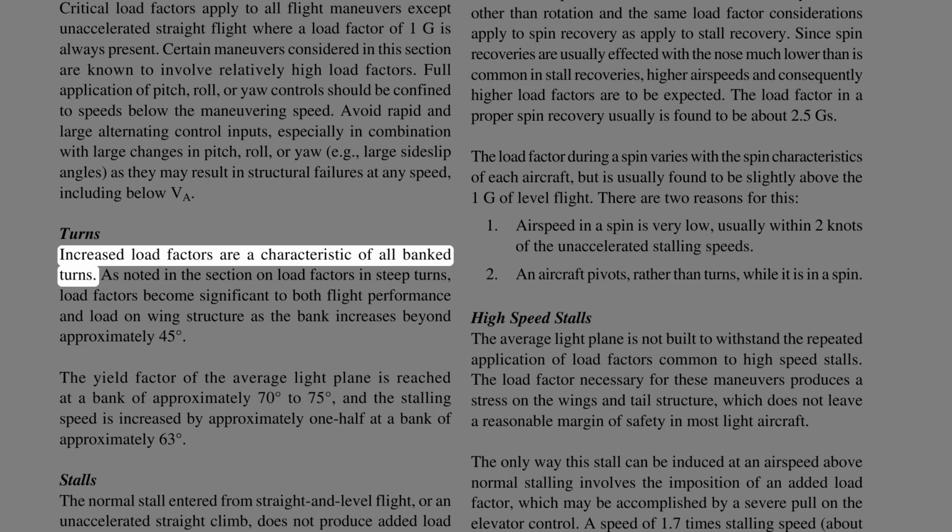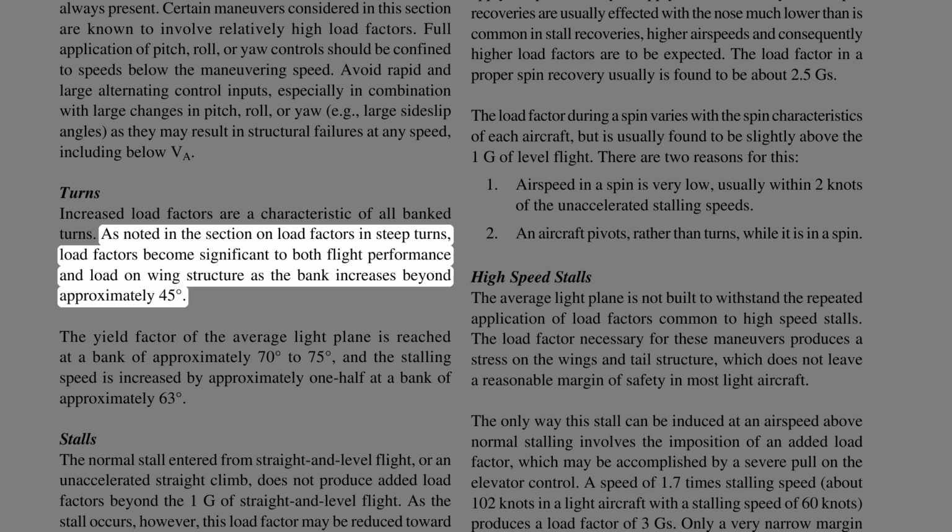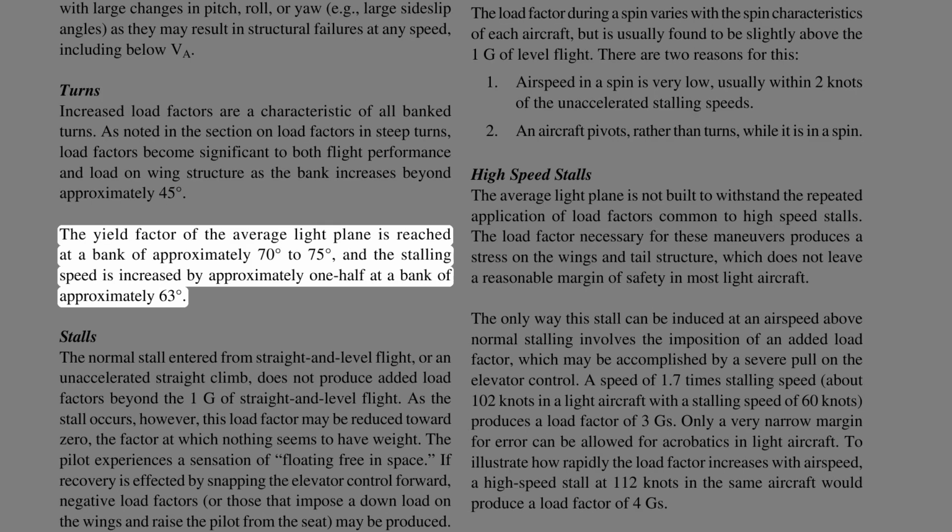Turns. Increased load factors are a characteristic of all banked turns. As noted in the section on load factors in steep turns, load factors become significant to both flight performance and load on wing structure as the bank increases beyond approximately 45 degrees. The yield factor of the average light plane is reached at a bank of approximately 70 to 75 degrees, and the stalling speed is increased by approximately 1/2 at a bank of approximately 63 degrees.